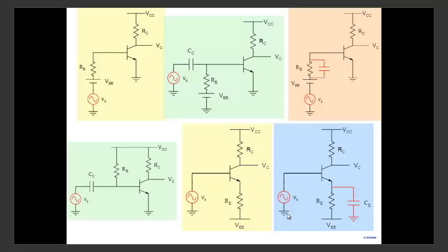And as far as small signal AC is concerned, this signal is going to go here, come here, and this part would be shorted to the ground under AC operation. If the signal frequency is such that the impedance of the capacitor is very small, then this point would be like an AC ground. And therefore, the entire signal that you see here would appear across the base emitter junction. That's what you want. So that could be another solution.